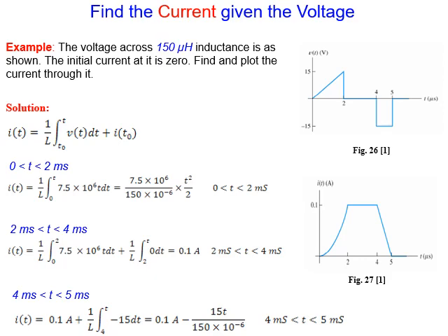The inductance, when we apply voltage across it, at the beginning it behaves as an open circuit, okay? And current starts to increase gradually until it reaches the maximum. The voltage goes to 0 and it behaves as a wire, a short circuit wire. Okay. Now see this example.